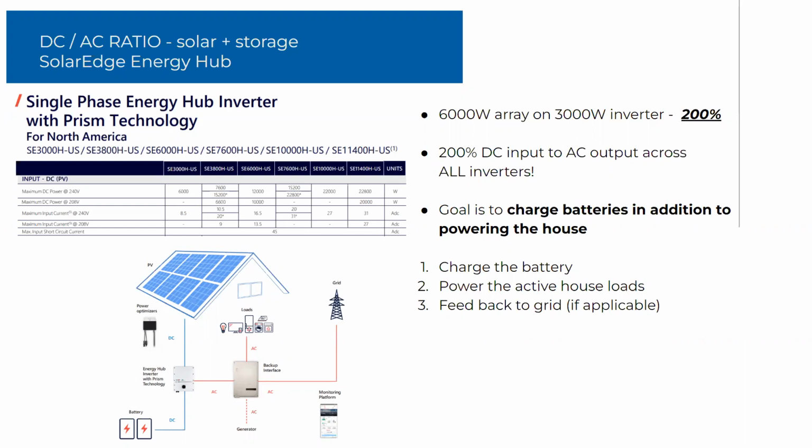And something else that is going to be more of a conversation these days is an EV charger. I'm definitely going to want a couple extra modules for an EV because that's going to be a larger continuously running house load. So 200% oversizing in this battery-based case, good to go.